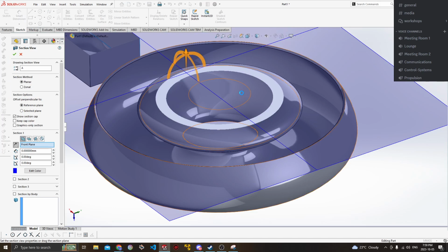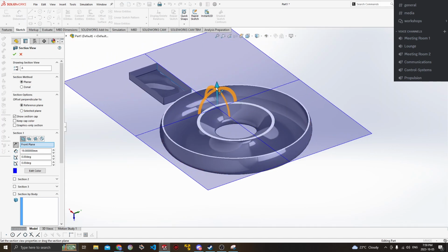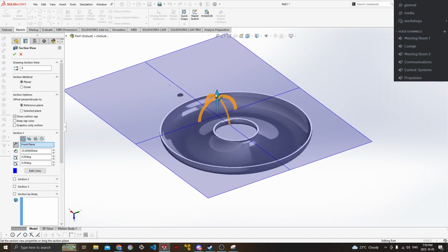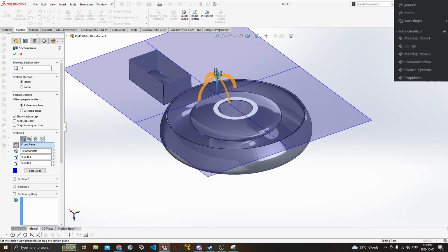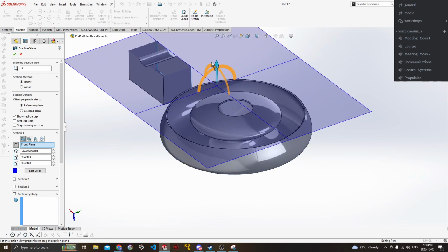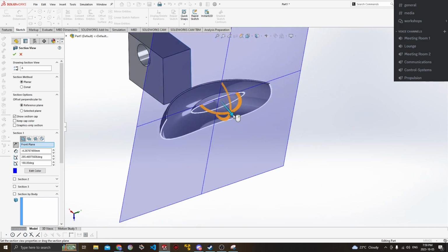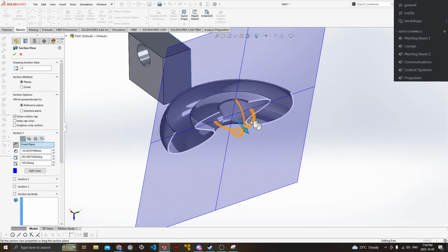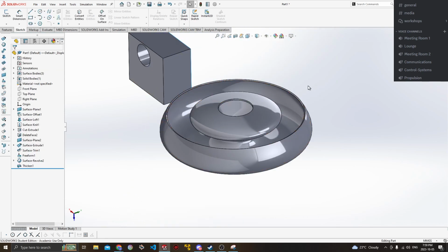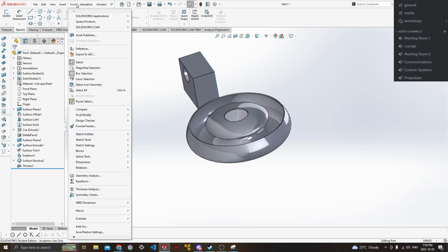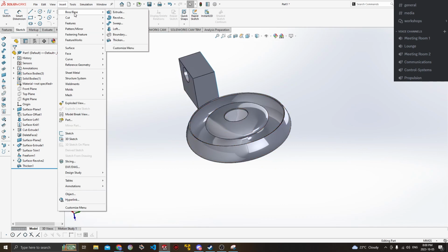How we can tell again is by our section view. So if you look through, you can see that the inside is that white color we expect versus our cube over there, which we haven't knit back together, which is not a solid, right? So if we cut this to the side, you can see very clearly that's a solid. So now it's a very simple way to create solids. Keeping in mind all of these different tools will help you out quite a lot.